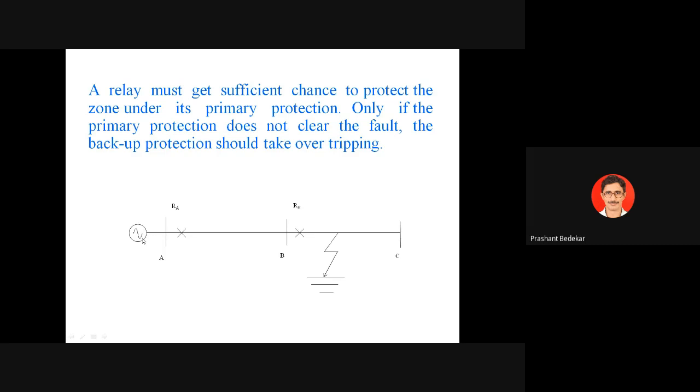Secondary side of relay contains very small amount of current, stepped down value of current. So, as the current is going through RA, RB both, even though the fault is in the section BC, it is sensed, identified by both relay RA as well as relay RB. Both relays come to know that yes, there is a fault. But